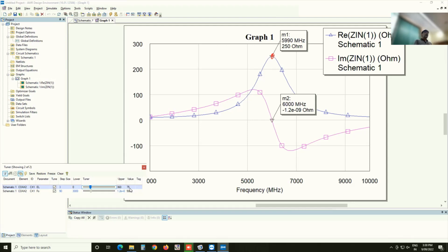If you have the frequency, or equivalently the wavelength, and then you have the actual physical length, it becomes a ratio of lengths, a dimensionless number. That ratio will change, which is exactly what I just demonstrated: the response at 6 gigahertz for a transmission line defined as 90 degrees at 6 gigahertz is the same as the response of a transmission line defined as 75 degrees at 5 gigahertz, because there is no difference between these two definitions.